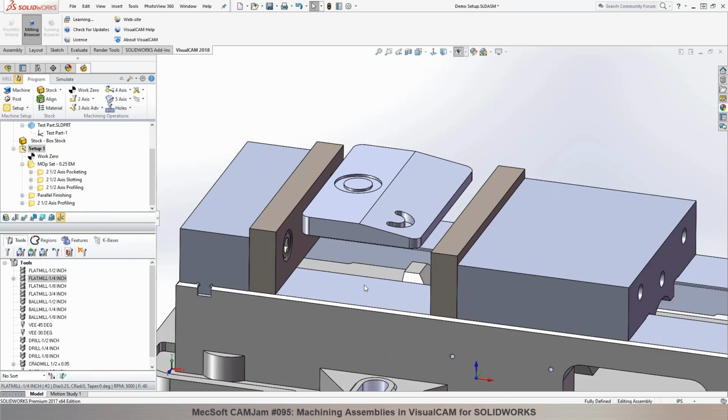Okay. So that's not in the actual G code. That is correct. Now we can output to very high precision. We could do 5 decimal accuracy or even 6 decimal. We can do double precision, but I believe 4 decimal is what's common for inch programming, and 3 decimal is for millimeter programming. Beautiful. Okay.